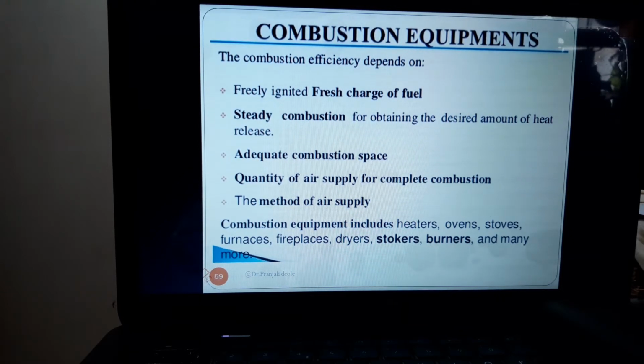Okay. The fuels are mainly bituminous coal, fuel oil, and natural gas, which are mentioned in the order of their importance. All are composed of hydrocarbons, and coal has as well as much fixed carbon and little sulfur. To burn these fuels to the desired end products, CO2 and H2O, requires air in sufficient proportions. It also requires a good mixing of the fuel and air, and a turbulence or relative motion between the fuel and air.